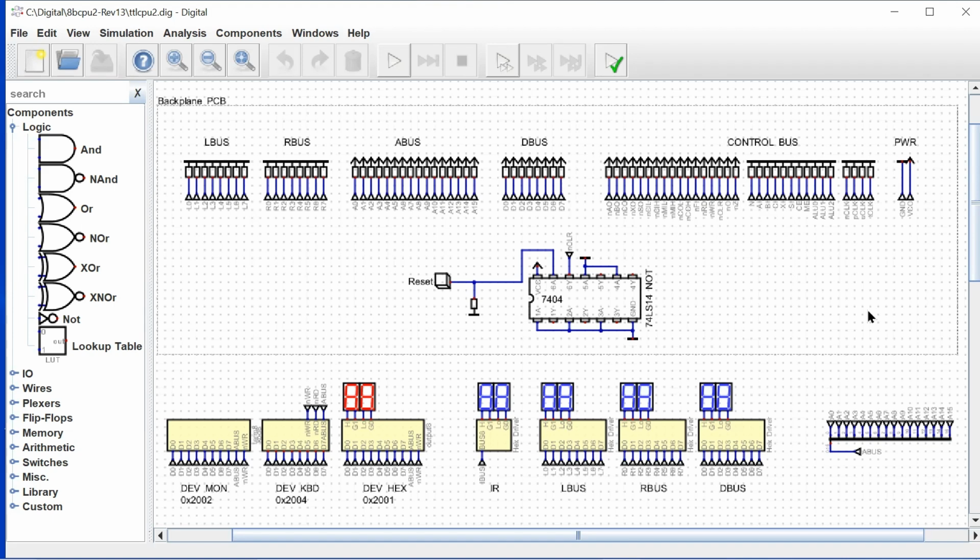I much prefer building a board at a time, having the manufacturing done, testing out the card, and then knowing that the card edge is complete and accurate, before having to throw that all into the motherboard, the backplane, at the beginning.